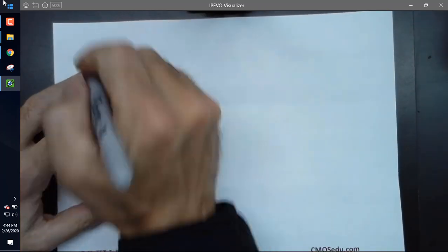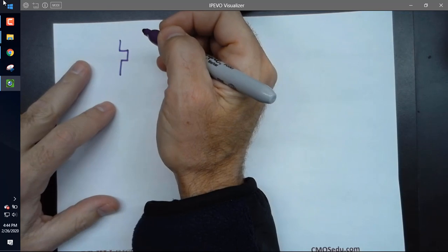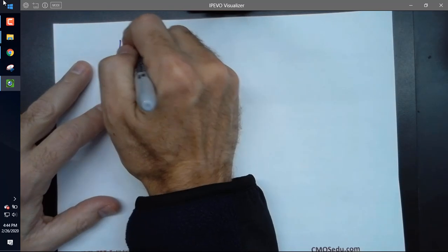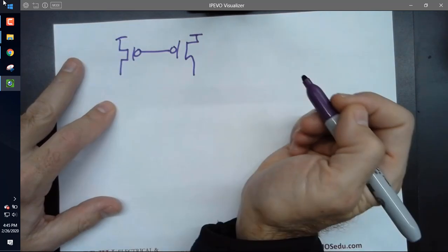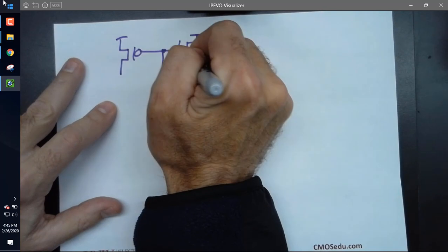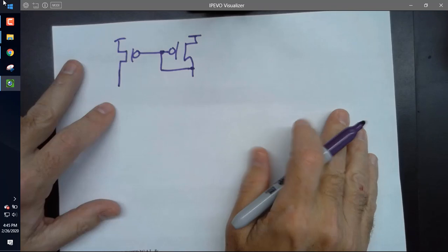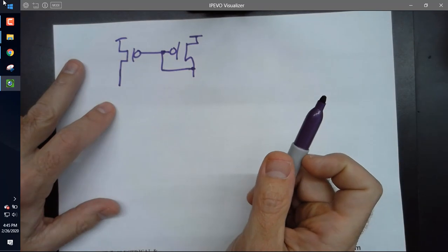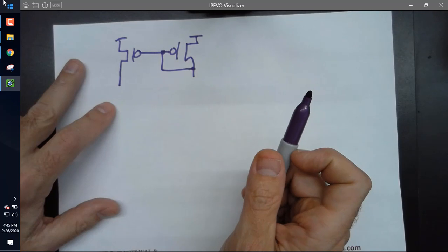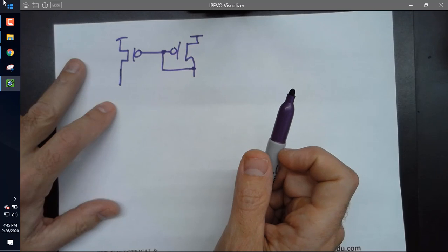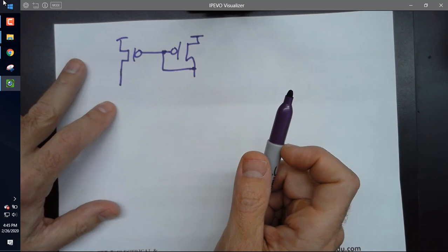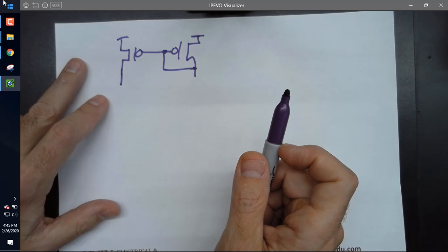Let's do the following. All right. I'm going to ask you some simple questions. I want you to burn them into your brain, all right? Of course, I want you to do that with everything I teach. First question. Does anybody remember how the threshold voltage changes with temperature? As temperature goes up, what happens to the threshold voltage? Goes down, it gets smaller, with increased temperature. What happens to mobility? Goes down. Remember, mobility goes down, threshold voltage goes down.